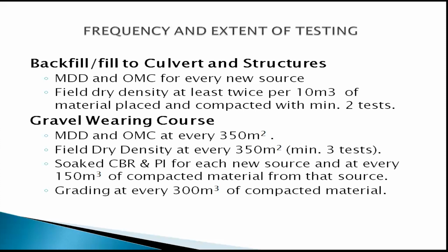So we move on to backfill to culverts and structures. Under section 7 and 8 of the standard specification for road and bridge works of the Ministry of Roads and Highways, we will have to do the initial assessment of the materials from the borrow pit and see if indeed it can be used for the backfilling to the culverts, maybe pipe culverts, box culverts, maybe retaining walls and all that. And the specification talks about using the minimum of selected fill material for the backfilling. So we need to do the assessment and see if indeed that material can be used.